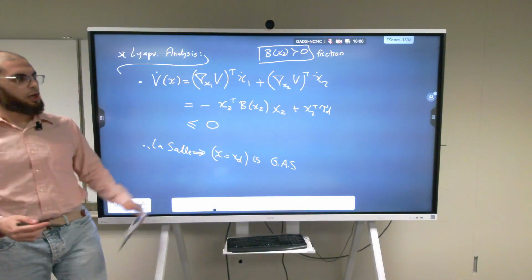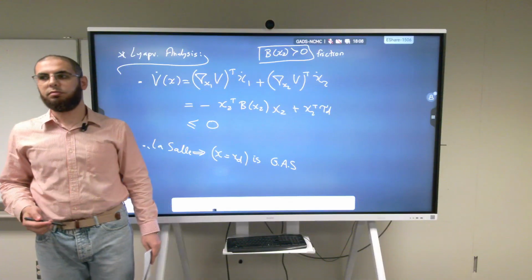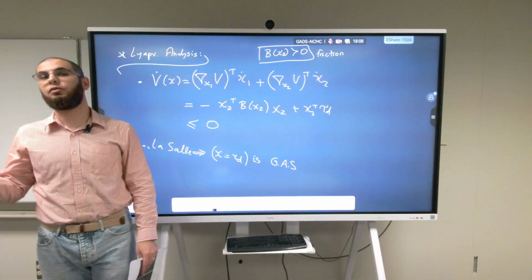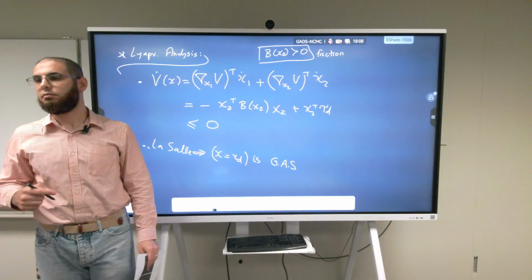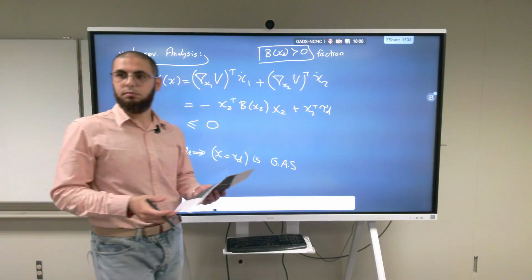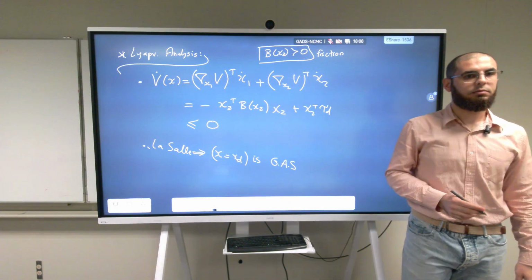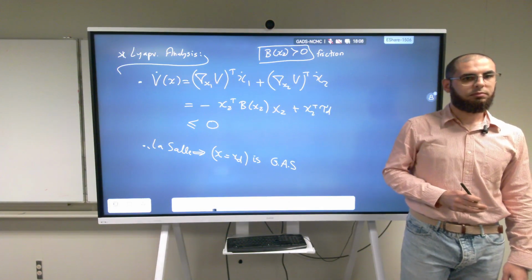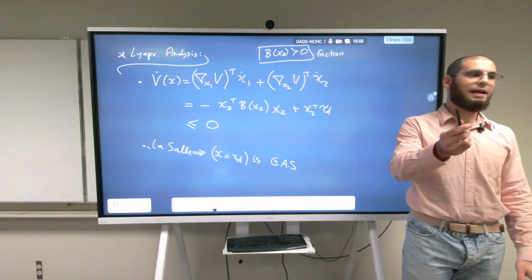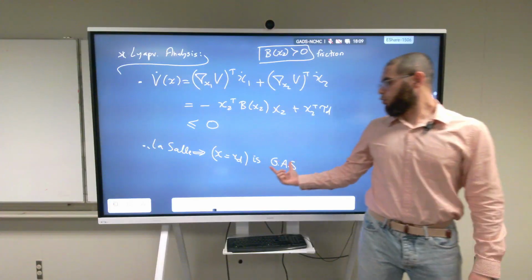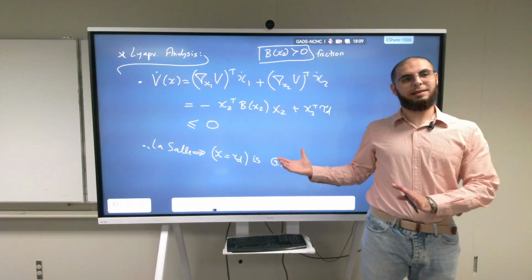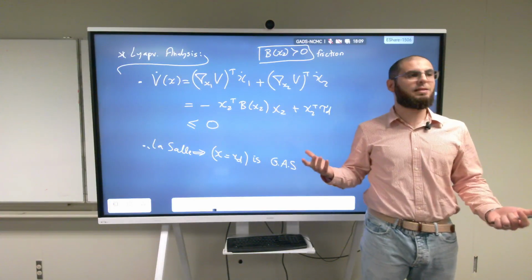Now the question is, why do we even need a derivative torque? Any ideas where you might want to have that? Controlling the damping. What do we mean by control the damping? For example, damping will have some settle time. Exactly. Control it. So here we have a mathematical proof that the equilibrium point is globally asymptotically stable.